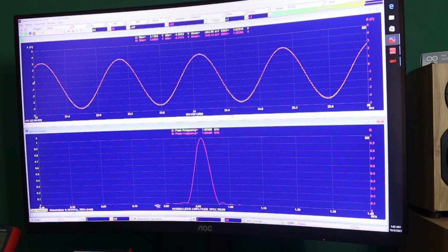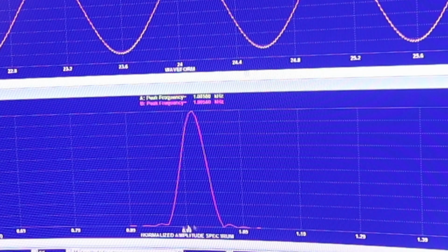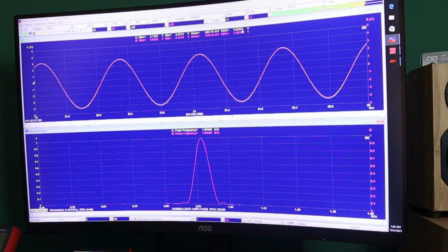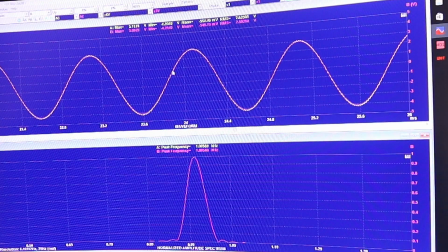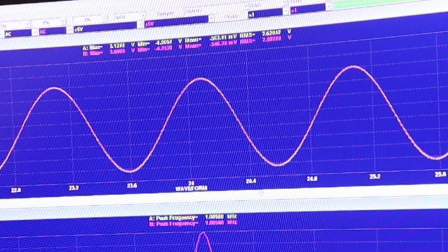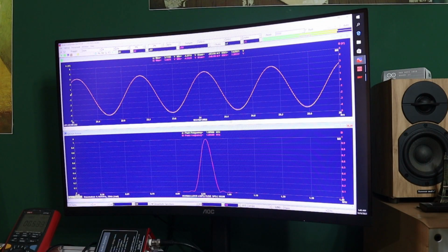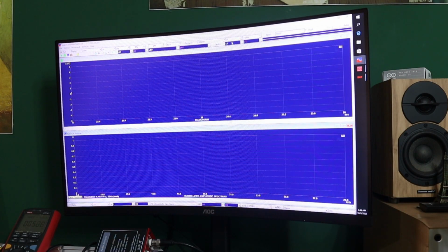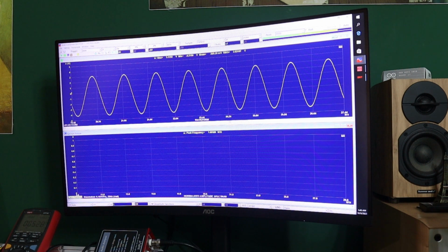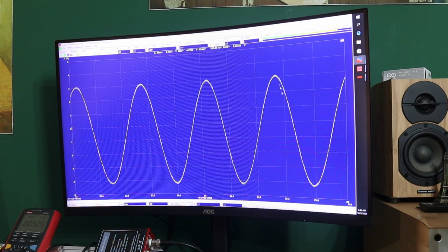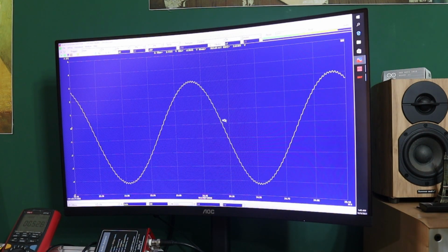And it shows that at 1 kilohertz, we get a peak signal with an amplitude of 2.62. So go back to the upper waveform. It shows here two signals. One is in the yellow and the other one is the pink one. Maybe I need to show to you the yellow one. This is the yellow one now. You can see here the clock frequency from the Class D. That's all right for now.